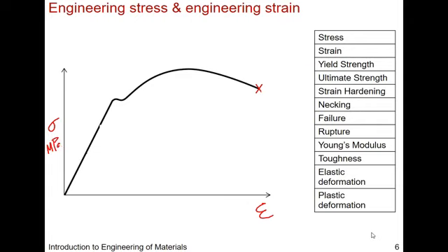Usually, if you're talking about a metal, we're talking about megapascals, all the way to gigapascals. We're talking hundreds of megapascals to 2 gigapascals for metals. And so typically, if you've seen those kinds of experiments where you stretch in tension, you're deforming the system in some way, you're applying some sort of load, and that's newtons per meter squared, per that cross-sectional area. So that's your stress and strain.